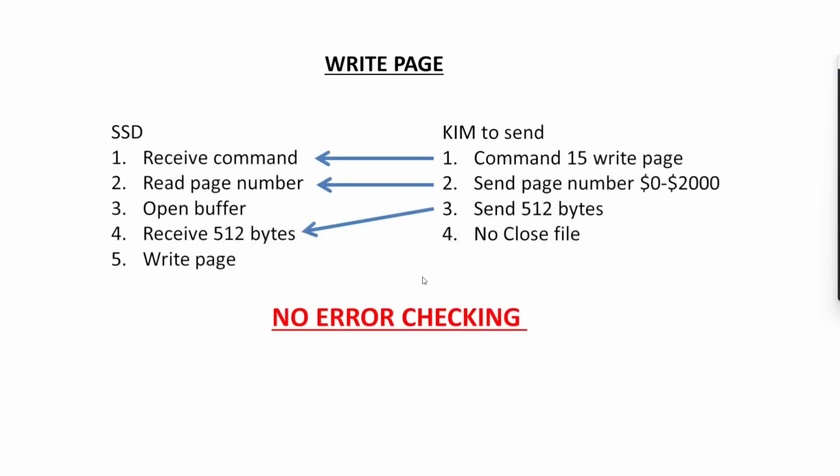So if you want to write a page, now this one is very dangerous, there's no error checking or anything. You can easily destroy the formatting of the data on the solid state drive with this. You could use this to basically format the drive, which you shouldn't have to do anyhow. You have to configure it to start up, and we do all that on the PC anyhow. So command 15 is write a page.